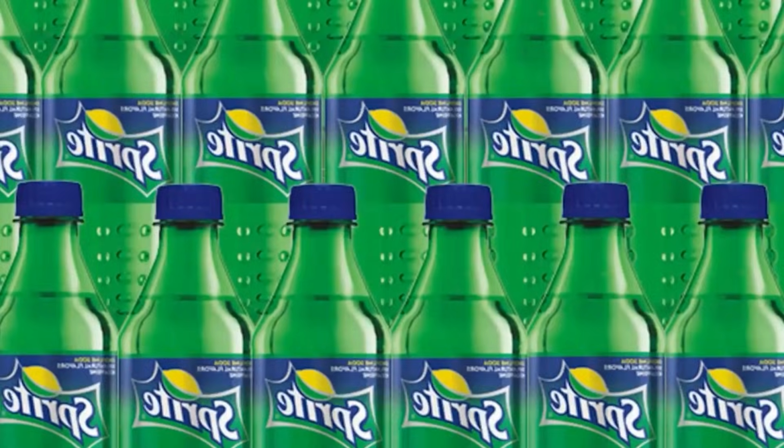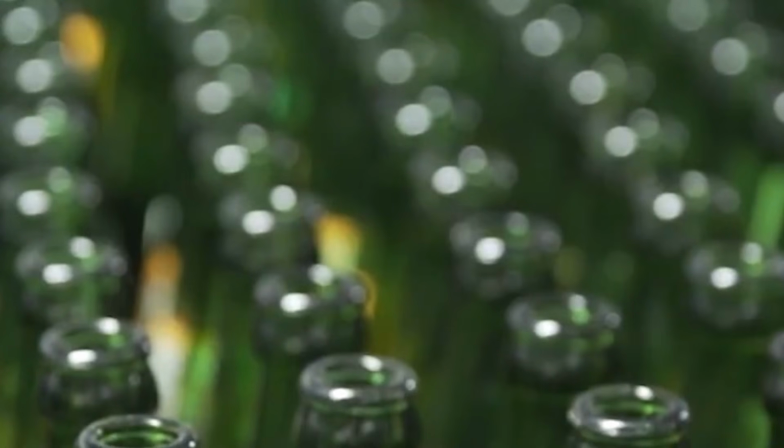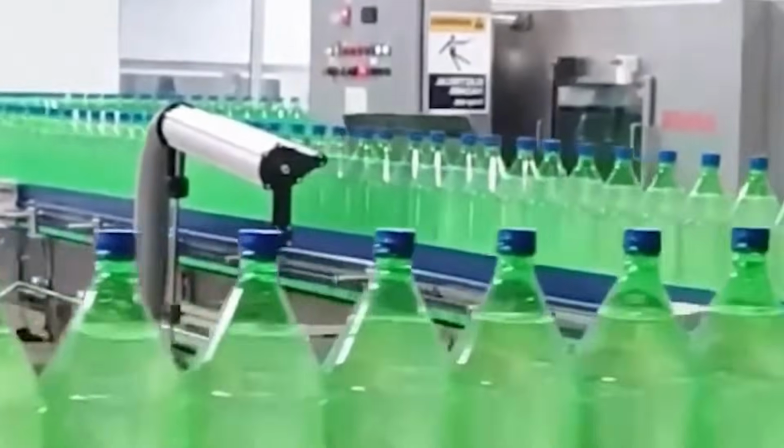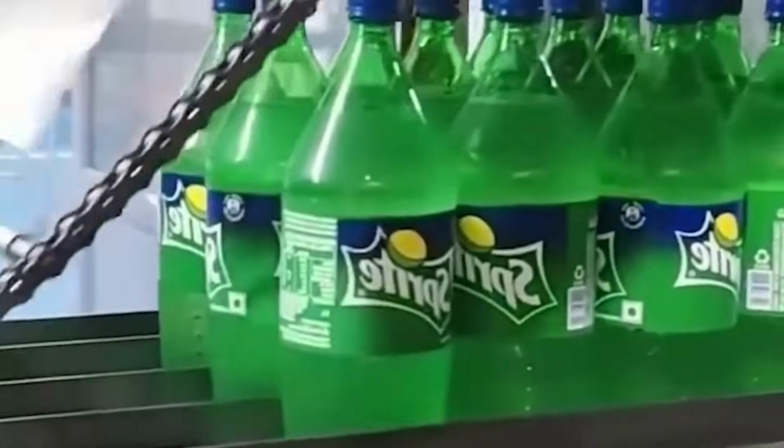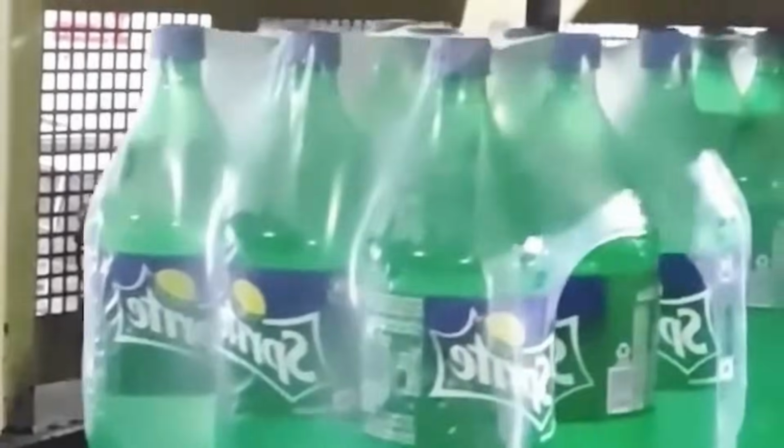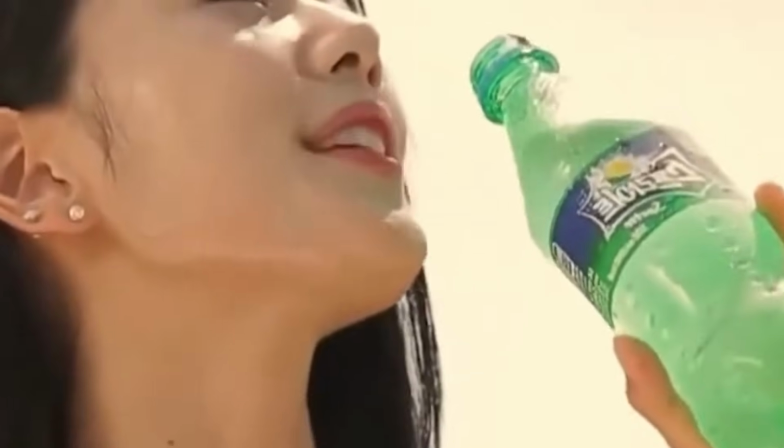Bottles are mechanically pushed into plastic carriers or enclosed in cardboard sleeves using servo arms. Cans are collected into 6-packs or 12-packs and overwrapped in shrink film. The multi-packs then pass through a shrink tunnel where hot air circulates uniformly around the film, causing it to contract tightly without damaging the product inside.